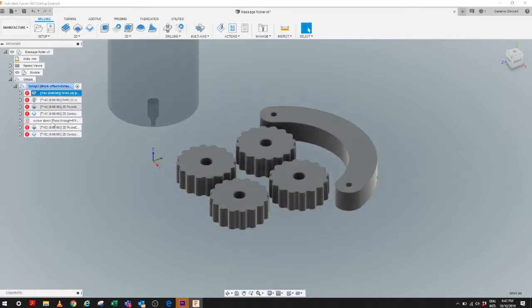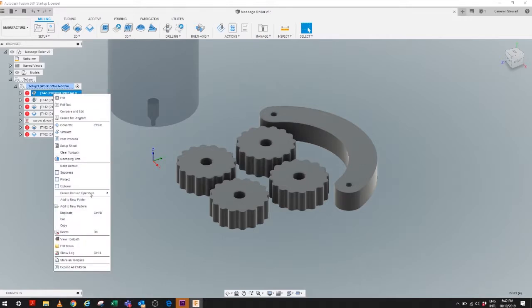And you can see there's a series of operations down the left here. These are using different tools, and you can see on the simulation what the tool head would look like. You can see that the head changes as you go down the simulation path. There's a 4mm cutter and a 6mm cutter. So different tools. To start, we don't need that guy, so we'll just delete him.